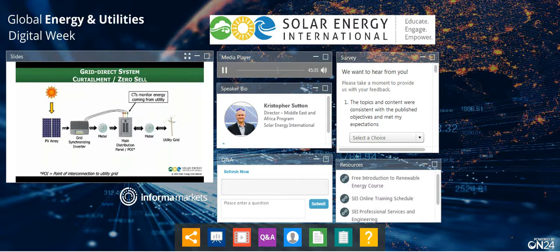Well, what we can do is use a system where we have to select the right inverter, and the inverter has to be able to basically turn off the solar or throttle up and down. It's not an on or off. We're able to tell it more or less solar based on what's available. Normally with a system like this, we'll put CTs, or current transducers, on the output of the main distribution.